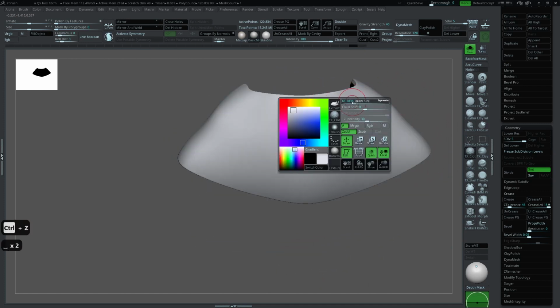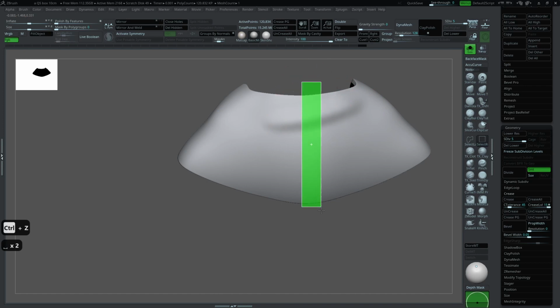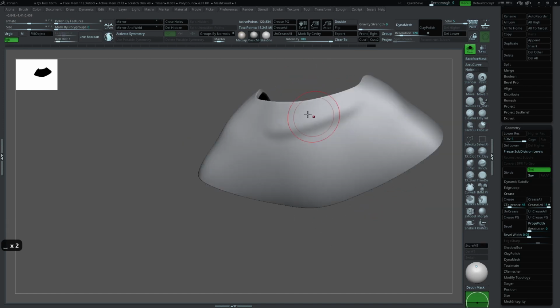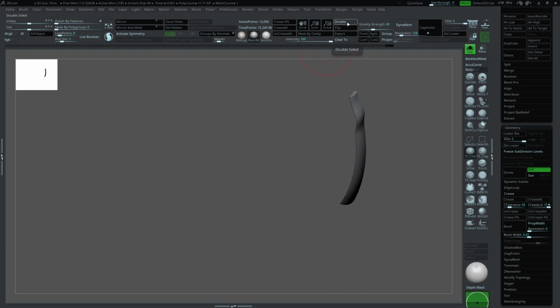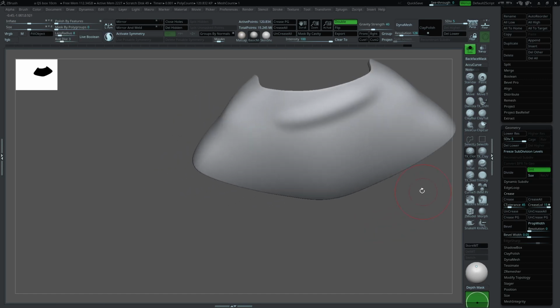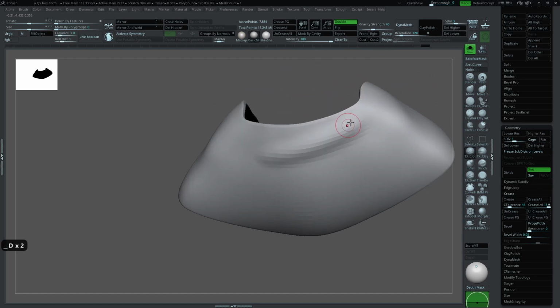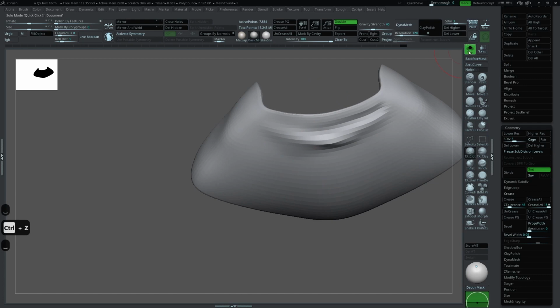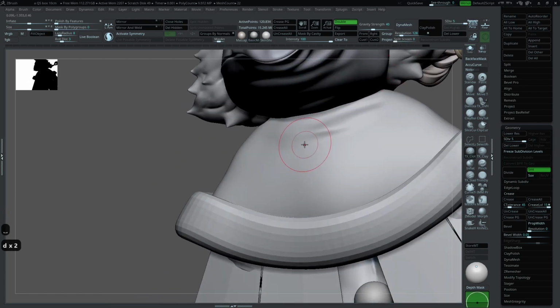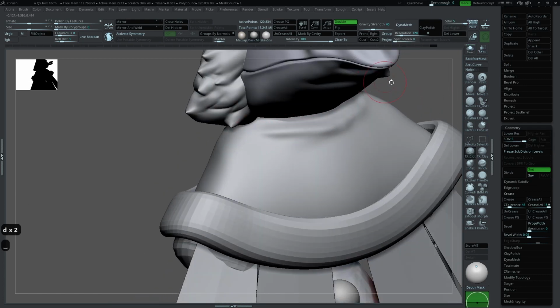And for clothing like this, if you sculpt, usually the back side is also affected. Sometimes it's better that way, but sometimes, if you look at the surface, at the intersection, and then you press Double here, it's good if it has the same thickness like this, but sometimes it doesn't have the same thickness, so you need to keep checking the intersection. So right now I'm adding some small clothing folds here on the back.